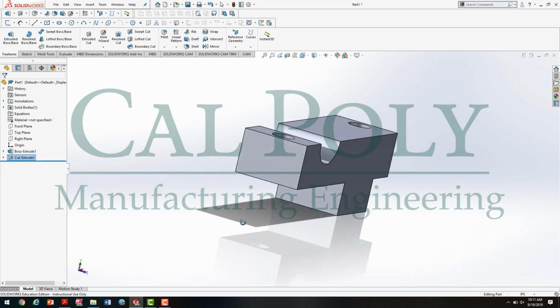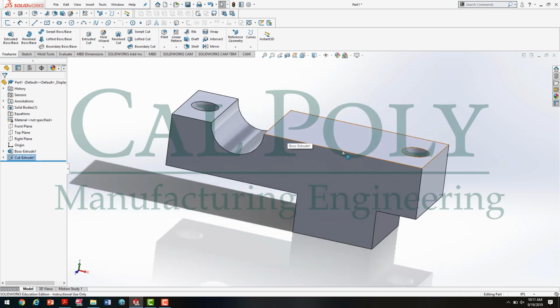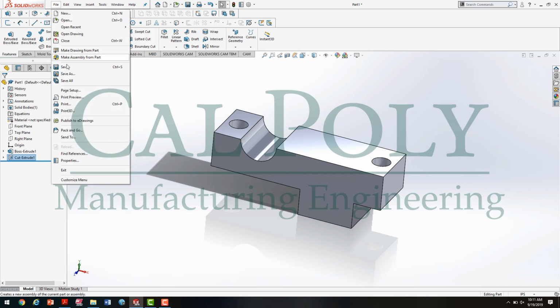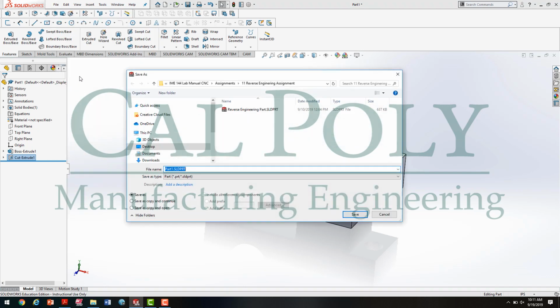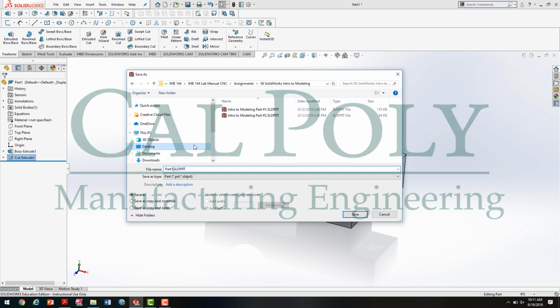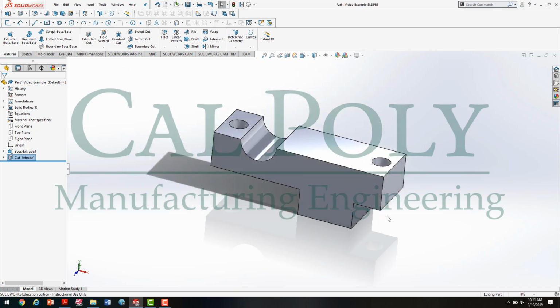Now I have some holes located in my part. At this point, I'm going to go File, Save As. I want to save my model. It's a good idea to save often just in case the computer crashes. It's been known to happen with SOLIDWORKS. And I'm going to go to my 144 lab manual, Assignments, SOLIDWORKS Intro to Modeling. I'm going to put part number 1, video example, and save. I would recommend just saving the part as your last name, and that way you know it's your model.